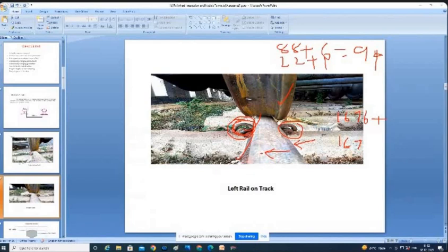That is why the permanent way persons always maintain one trackman. This trackman's duty is, whenever there is a slack or missing Pandrol clips, to insert them and bring the track back to normalcy. That means the flange force you are applying pushes it out and damages it. Again the next day, the trackman will make it ready and bring it back to 1676 by inserting the Pandrol clip. Clear to you? Okay. What is the influence of the flange force on the track? It is clear?